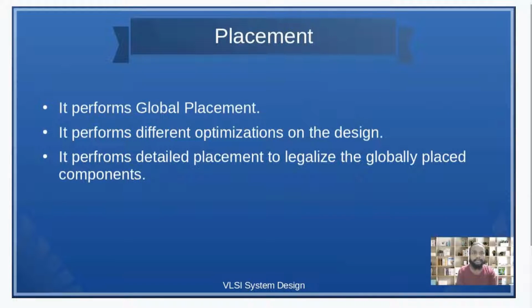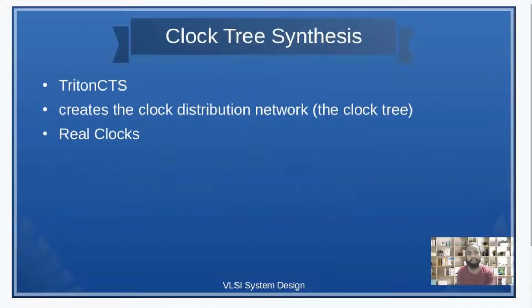After this stage, there is the placement stage where the global placement and detail placement is done, and different optimizations are done on the design. Then the clock tree synthesis is done, where the real clock tree is generated using the tool TritonCTS. Here the static timing analysis is done using real clocks.